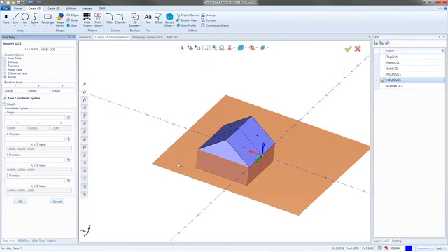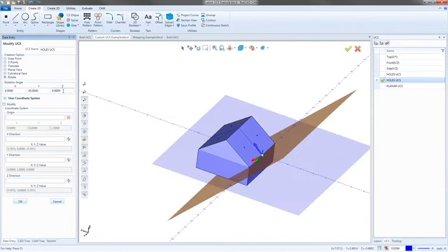So now the rotation is all here. It's just like the translate. We don't have any geometry to select. This is just the plane itself. How are we going to rotate it? So we could actually come in and say, I want to do a rotation angle of, let's say, around the y-axis. We'll say 45 degrees. And I don't think that's sitting at 45. So that brought me to 45.